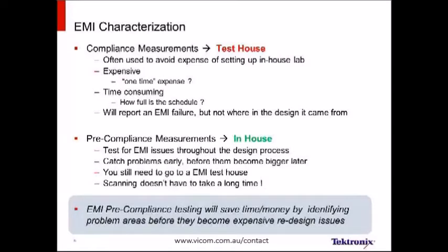Pre-compliance measurements, on the other hand, can be done in-house. Testing for EMI issues throughout the design process is a really positive thing. We can catch EMI problems much earlier in the design cycle and fix them before they become a bigger problem later on. No one wants to fix an EMI issue when we've already got the product in its final packaging, for example. But we still have to go to the EMI test house. Even if we do pre-compliance scanning, we ultimately have to get our certification from the test house itself.